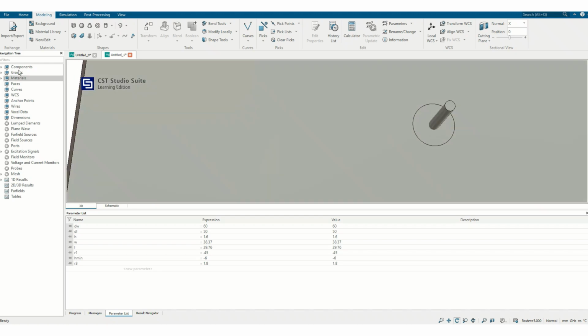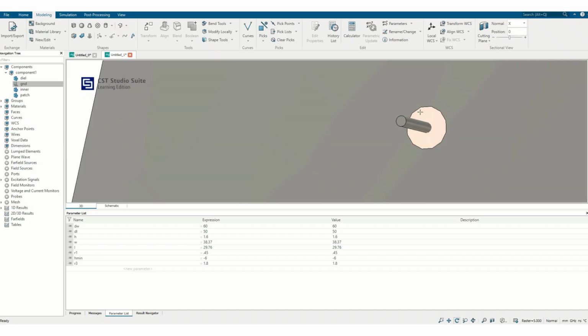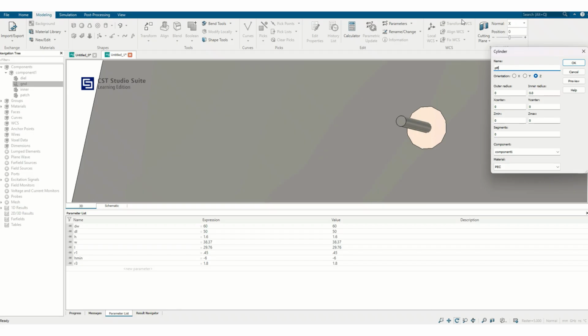So now we have this circle. Now I'm going to subtract this from the ground and this portion. So now you can see that the inner conductor is not in touch with the ground plane. My next aim is to draw the PTFE material. Its radius is from R1 to R2. X center is 0, and Y center minus L by 4. And Z min is from H min to 0. It has to go from this position to this ground plane, and its material is PTFE.